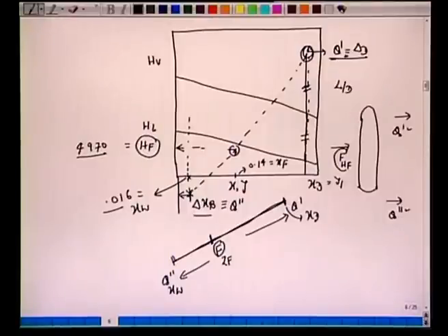You can mark this point, or you can write down. You can know the enthalpy for these 2 points. You can make use of this to mark this Q' point. From this Q' point, of course, we can get this condenser load. Similarly, once you know this point, we know this feed, we can extend this line. It will be a straight line. It will intersect at xW. This will give you Q'' point, and from this one can also calculate Q boiler.